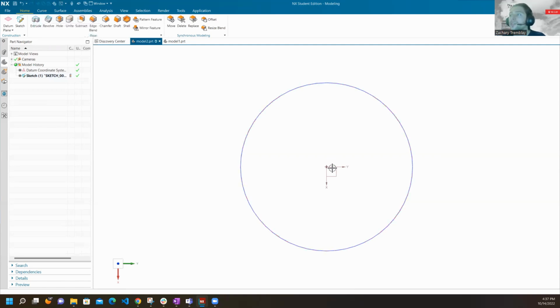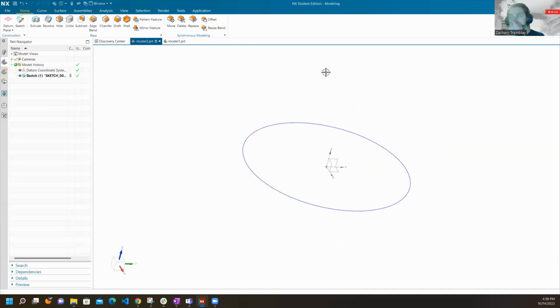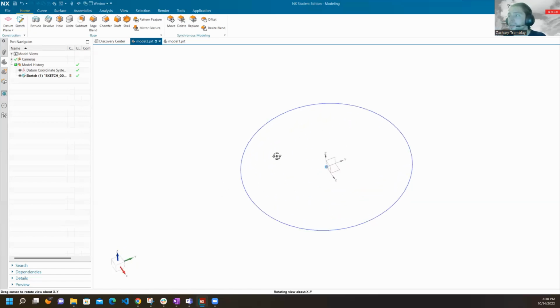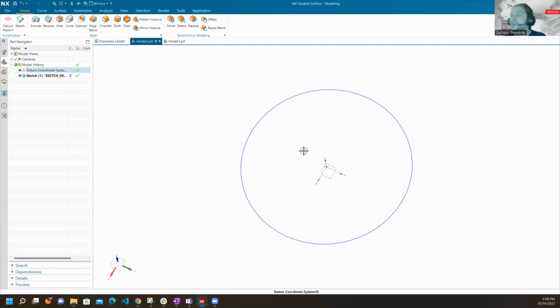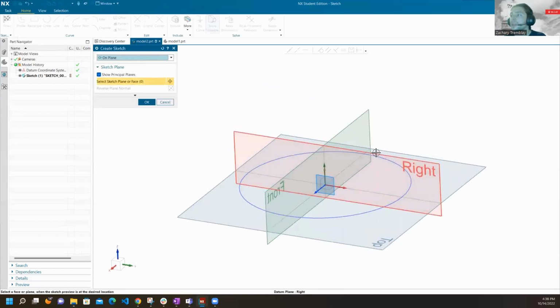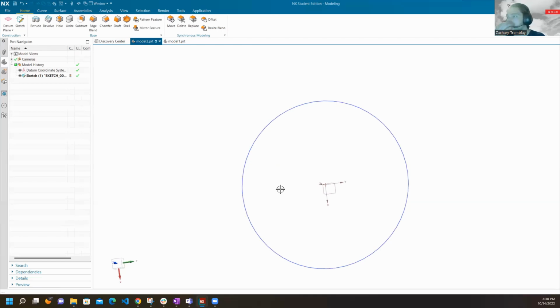So to extrude this shape, well, actually, first, what an extrusion is, is when we take the shape and we translate it perpendicularly to the sketch to create a 3D shape. So something perpendicular to this sketch would be the Z direction. And this all depends on what face you chose when you sketch for the first time. So if I want to say sketch again, depending on the face that I choose, the extrusion is going to be in a different path. But now I'm going to cancel it to not create another sketch.